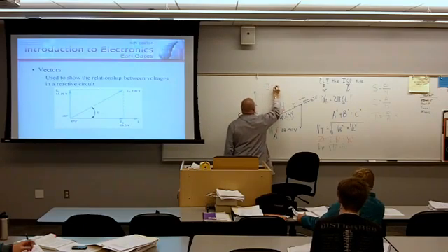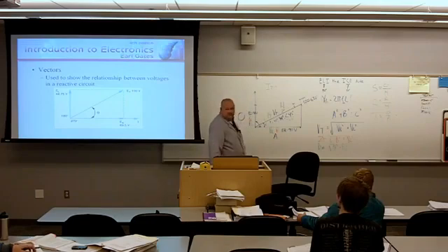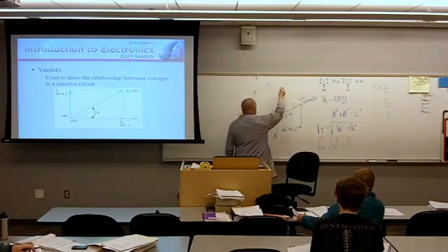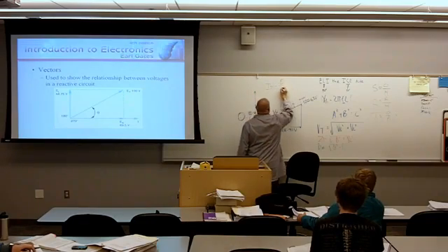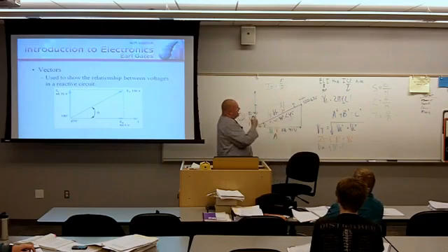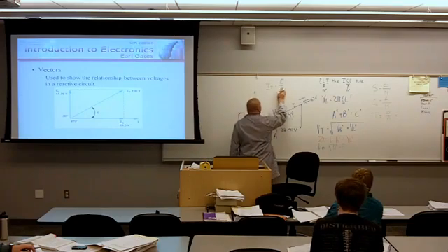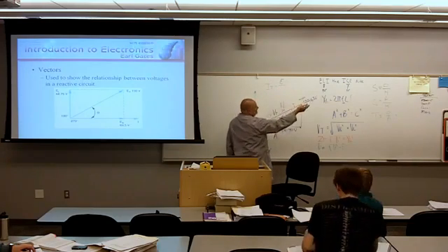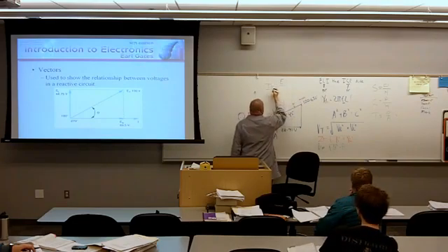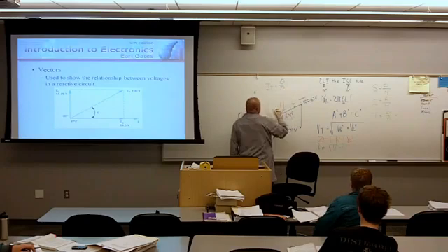IT equals E over R. In an AC series circuit like this, do I have R anymore? Close. You have R and X sub L. And what do we call the combination of that? Z. Well, you need to find X sub L first. Absolutely, that goes without saying. But this formula for IT is going to work as long as it's ET over ZT.